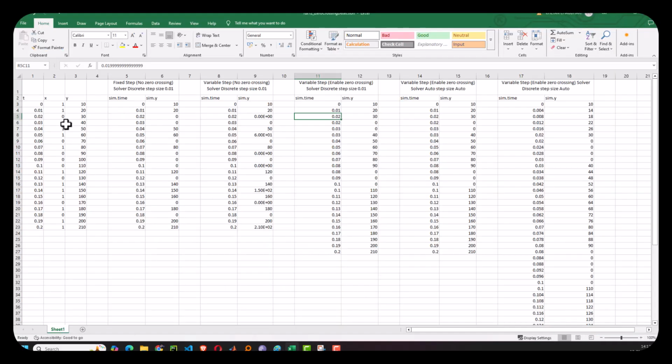So again, if I explain for this first two, here the input was constant 1 and 1. So the solver identified there is not much change in the input and processed it very easily. But in the next step, from 1 to 0 change happened, then the solver identified this is a crucial point. Here I am getting the zero crossing detection. Then I will take one more step extra to identify the change point. So that's why it took one step extra for this particular timestamp, and then the next step on this particular timestamp.